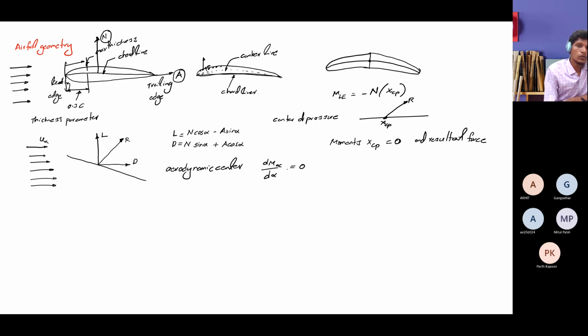Okay, you may get a question whether the center of pressure is fixed if you change the angle of attack. No, the center of pressure also varies, but it does not vary significantly for small changes in angle of attack. After a certain angle of attack, it varies very significantly. In the same way, the aerodynamic center also does not vary significantly for small angles of attack.